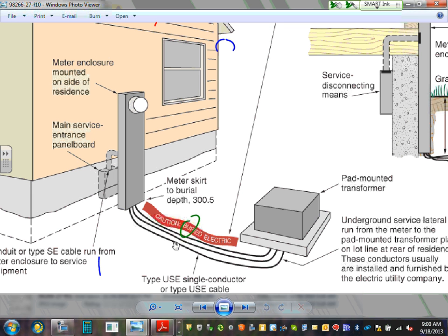The way it goes, first the cables here, 18 inches minimum. Now we're talking about minimum here, 18 inches, and then they put your tape at a foot, 12 inches, a foot above the cable. So you put your cable, bury a foot of dirt, put the tape, and then continue burying. When you put a foot here, that will leave you with 6 inches, right? 6 plus a foot, 18. So from here to here will be 6 inches. Does that make sense? For a total of 18.